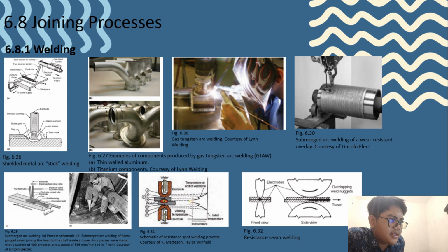The focus here by necessity is only a brief overview of the wide-ranging technologies of welding, brazing, and soldering. A general comparison of the basic joining technologies is summarized in table 6.7, which is not very necessary. The main distinction between welding, brazing, and soldering is the nature of the bond. In welds, joining occurs by interdiffusion of atoms from like base material and forms a bond.